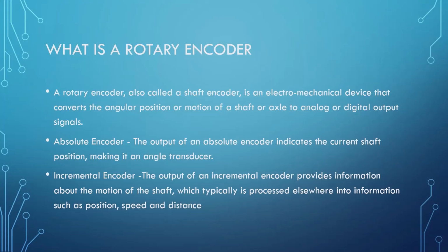The other type of encoder is the incremental encoder, and that basically increments positive or negative. When you turn the shaft to the left, it's positive, and when you turn the shaft to the right, it's negative. What we're working with is really an incremental encoder, so every click of the turn either adds one or subtracts one from the value.